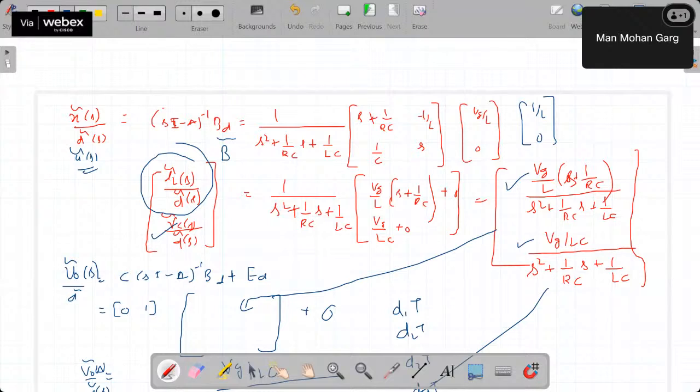So in that case, we will write those equations and get one particular model for that particular mode. Then similarly for the next mode, the third mode, the fourth mode, right? So individual modes we have obtained. Now we also do not know for how much time each mode is operating. Let's say the first one is for T1 period, second is T2 period, third is T3 period, fourth is T4 period. The sum of all those is capital T, right?